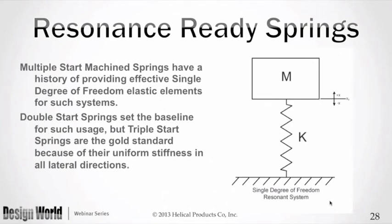The reason you would want to triple start is that double-started springs are, in a lateral sense, different in their stiffness, both in translation and in bending, on orthogonal axes. So when you're in line with the ends of the springs, it'll be one stiffness, and if you're 90 degrees away from the ends of the springs, there'll be a little different stiffness. And that can cause trouble in a dynamic system or in a resonant system. So the gold standard right now is the triple-started machine spring, because it is uniform in stiffness, both in translation and in bending, in all directions. And this is a good use, a very good use of the multiple started machine springs.